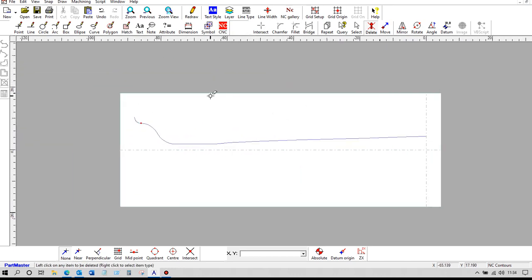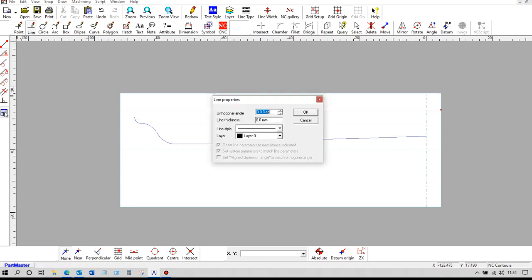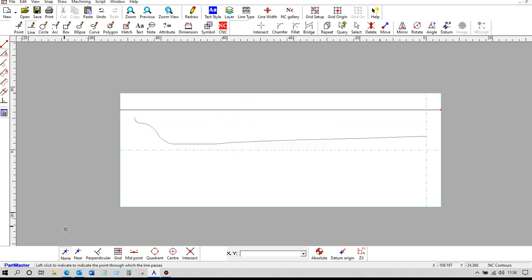okay, so now we can do the same thing and create some lines. So this time, this line here, it doesn't matter particularly where it is, and you'll see why in a moment. So now change the angle to 90 degrees, go into near snap, and put the line there. Now go into intersect, and oops, clip items.